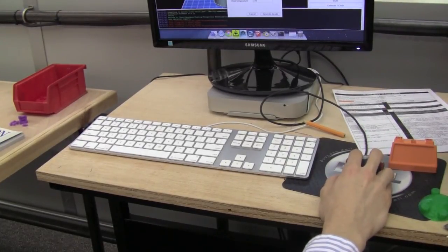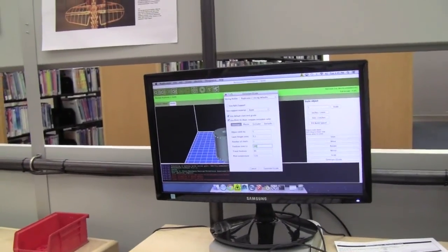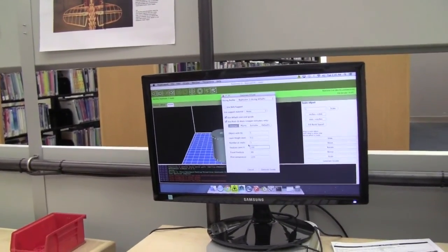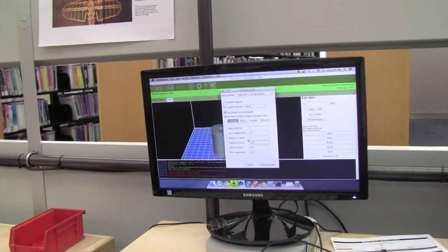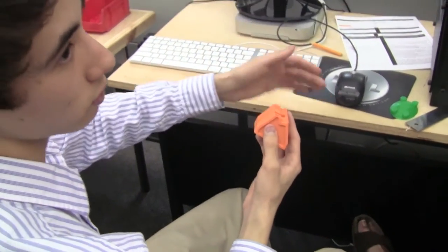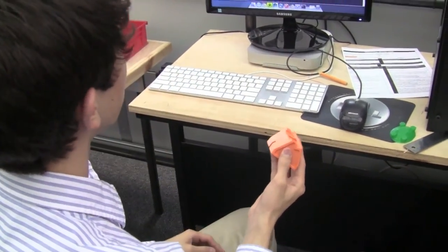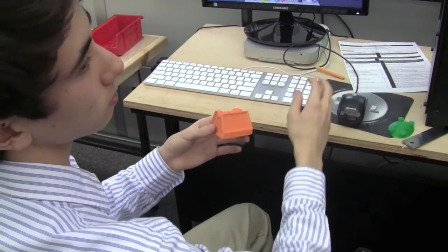So once again, this is a trade-off between quality and speed, which is what most things are. For this quality print, I did 45 millimeters a second, like I just said, and generally 60 and higher will yield a rougher result, but again, it takes less time because your extruder is physically moving faster. Right, so that's feed rate. That's really important to keep in mind.